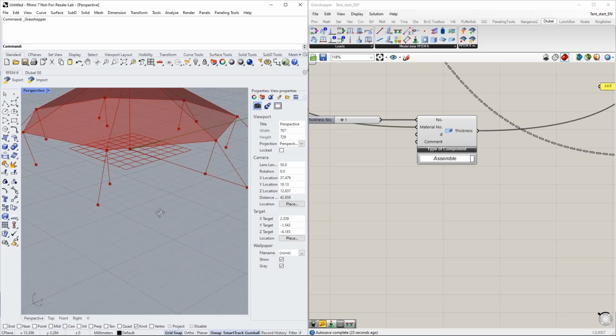And I want to rotate my nodal supports in a way that at least one local axis of this nodal support is directed in the same direction as the member is directed. So I want to have the support forces in one value and not spread over 3 different vectors. I think you know what I mean.